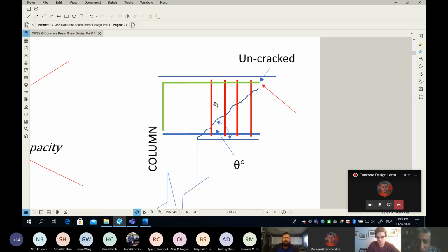Look at the stirrup. The stirrups are going from the bottom to the top, hanging on the stirrup hanger, those in green. Now, if this crack is to open, can it simply fail without snapping the stirrups? No, the stirrups must be snapped for this beam to fail. And that's what increases the shear capacity.